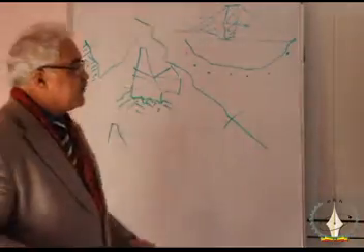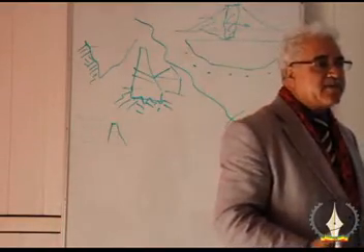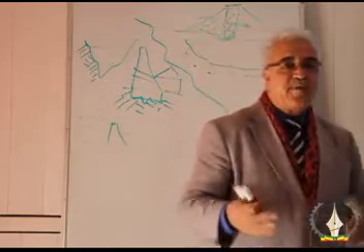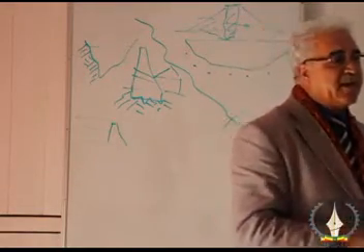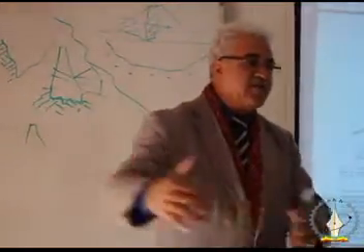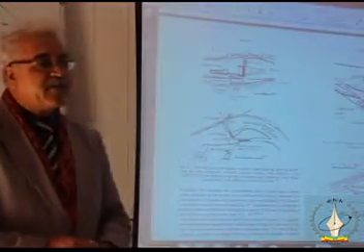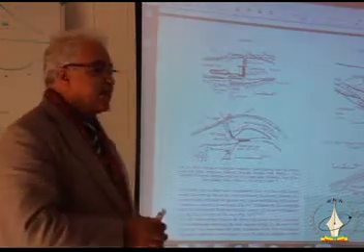But in the case of low-head hydropower plants, normally you are not looking for a big reservoir to store water, because in many cases they are run-off river schemes, which means that the water comes in the river, goes through the turbine, and leaves. There is no big storage, maybe just a little bit.